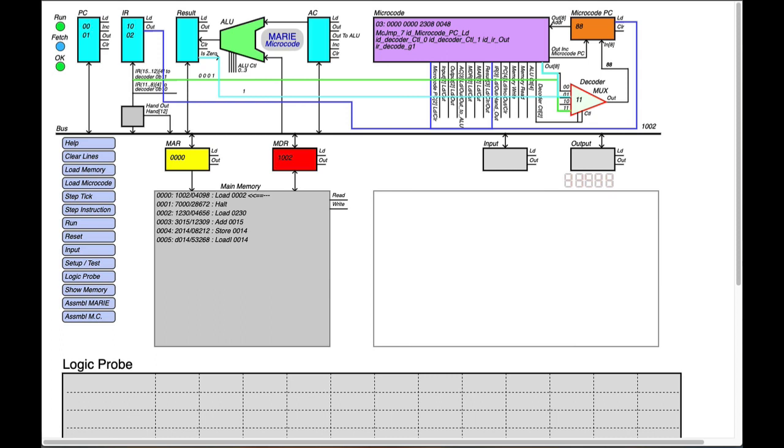So let's look at what happens in that instruction. First of all, we have to have the origin of where the instruction is in memory. And that's an 88, which is a 1 3 zeros and a 1 3 zeros. So that's where it's going to be ending up executing next. And this is the set of steps that it's going to run through to actually run this instruction. And I'm giving you 2 instructions, the instruction for a load and a store, and we're going to work through those in detail.